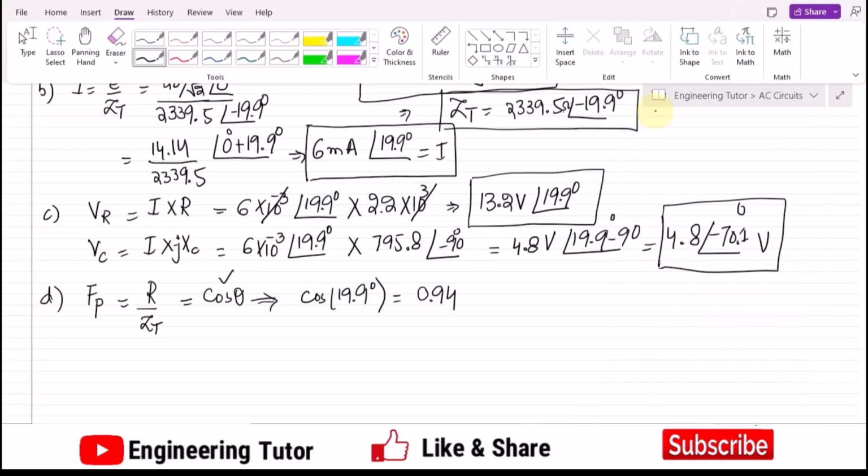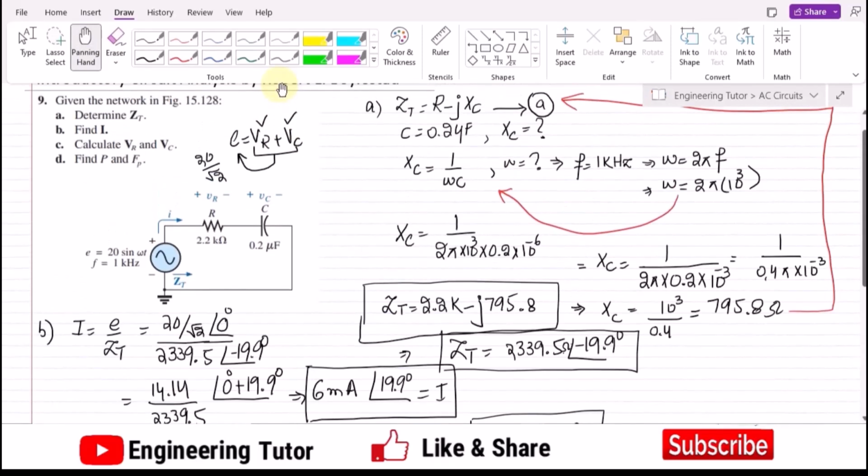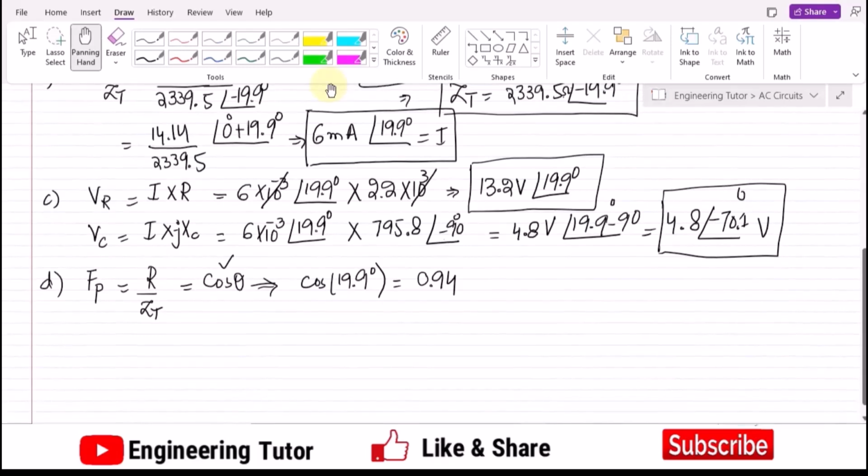And as we can see, this is the capacitive circuit where current always leads, therefore I have told you earlier that we have to relate it with the lagging or leading characteristics of the current. So as the current always leads in the RC circuit, this is 0.94 leading. Okay, you can also see it from this formula that it will give you this value.